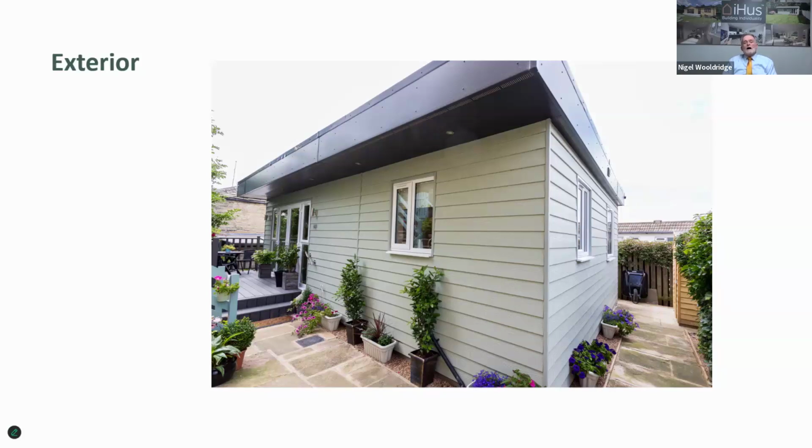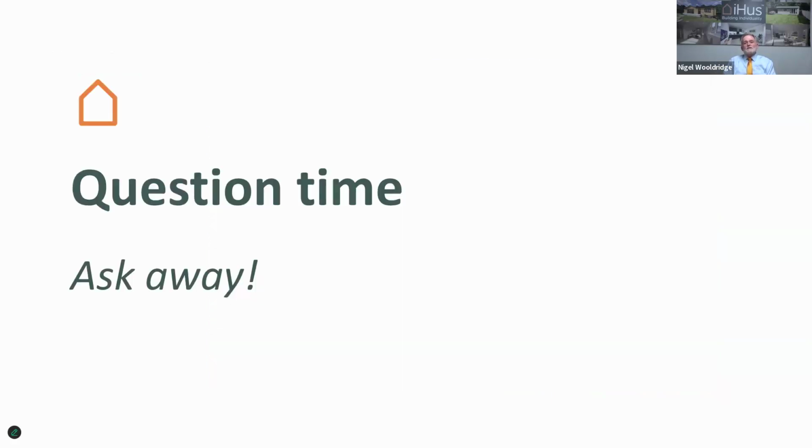Another good question. Legally, for building, it's 600 millimetres, in old feet and inches, 2 feet. However, if there is means of egress, so let's say the back of the building's gone up to the bottom fence, if one of those windows is means of fire egress, it's 750 millimetres. We normally state, as a rule of thumb, a metre.